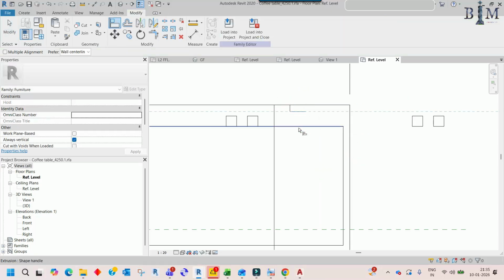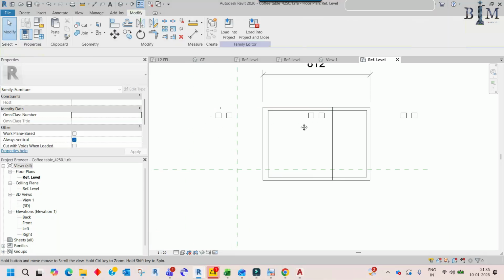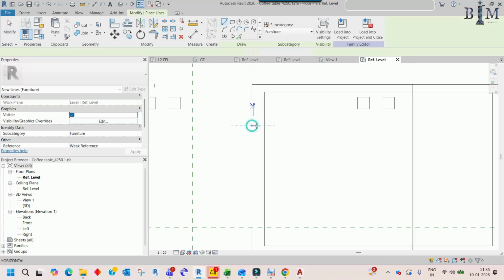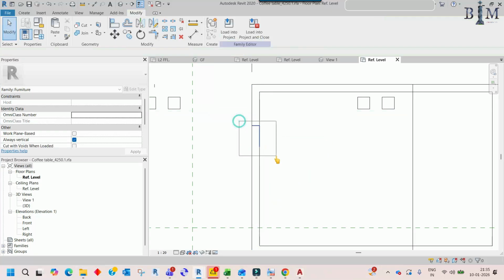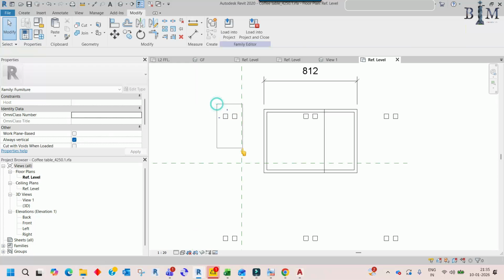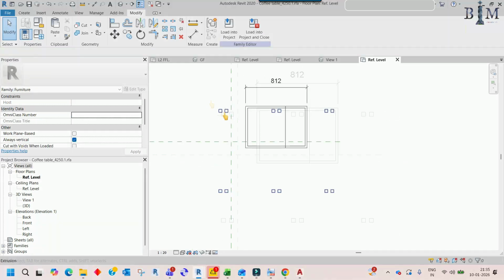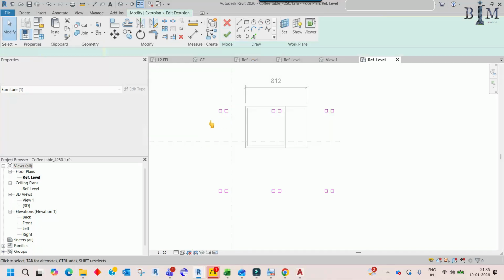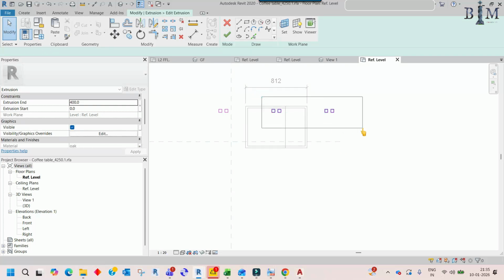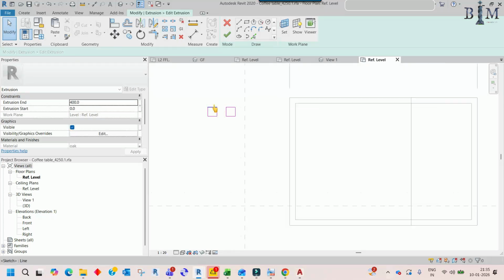Okay, so align the line up to this, and here also Li 25, and here up to this I need the alignment. So here this element I don't need, so select the element, and here edit extrusion, I don't need anything, only this and only this element I need.